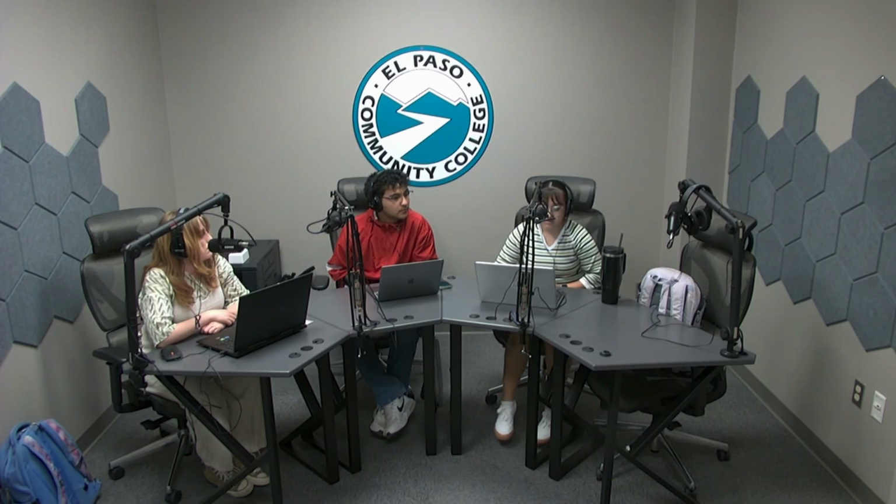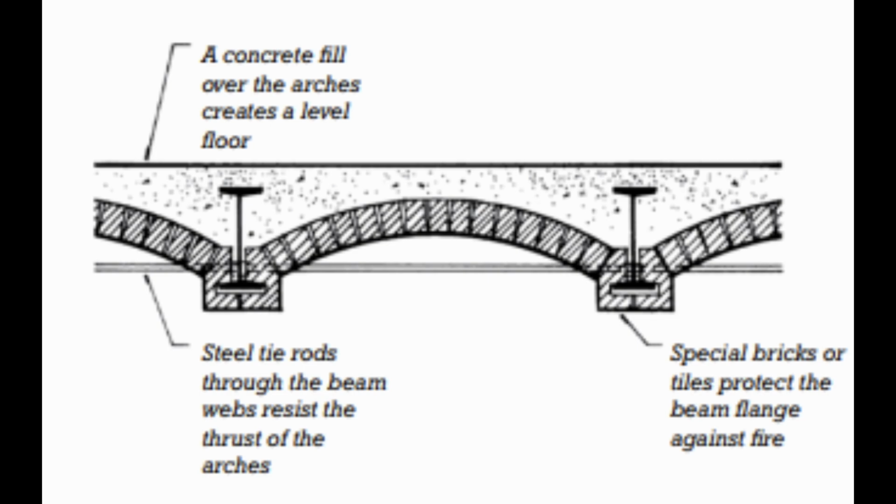They also mention the floor and roof decking: shallow arches or brick tile work constructed between support steel beams, tied with steel tension rods and filled with concrete to produce level floor surfaces. This method is heavier than metal deck and requires larger framing members with intensified labor.